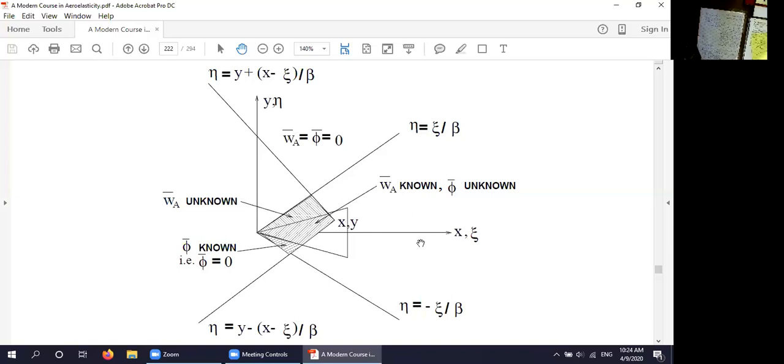Moreover, any disturbance behind the wing, and there is a disturbance behind the wing once the wing passes through the air, cannot catch up with the airfoil because any disturbance back here moves at most with the speed of sound, and this is moving faster than the speed of sound. So we don't need to think about what's happening behind the wing. We don't need to think about what's happening ahead of the leading edge of the wing. We certainly need to worry, however, about what's happening on the wing.